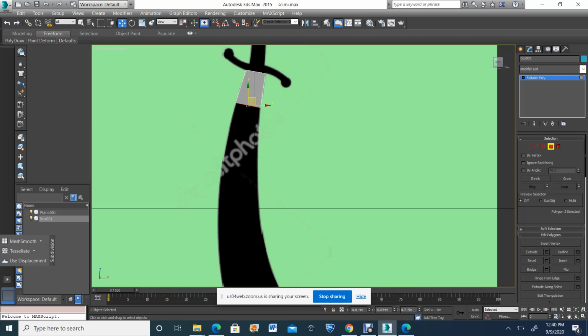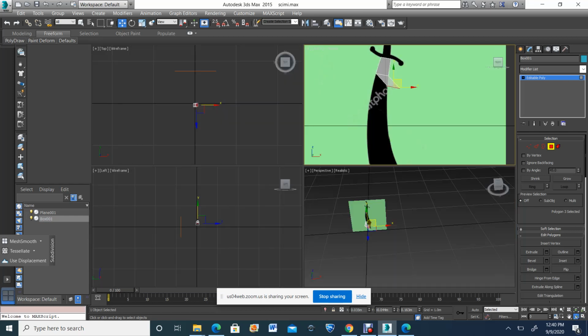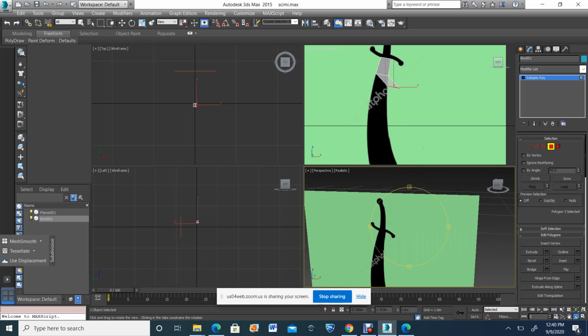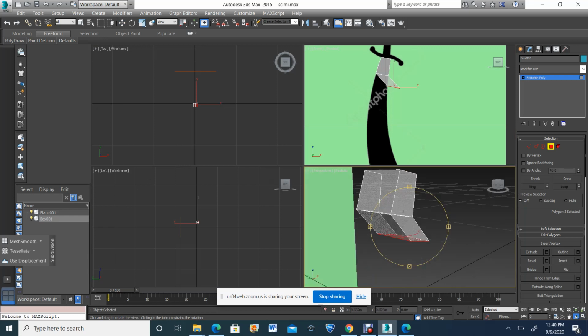So right here, extrude, I want to keep it consistent, so I'm going to click on the settings one, and that's going to let me decide how much I want to extrude it. So that much. That's a good starting point. And before I do that, let me zoom out, zoom extents here, Control R for rotate, and see if by some chance I've grabbed any other polys that I don't want.